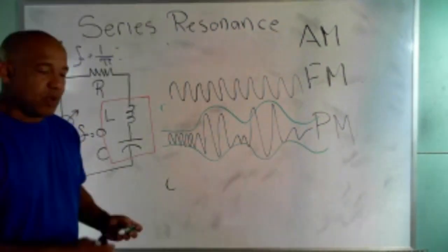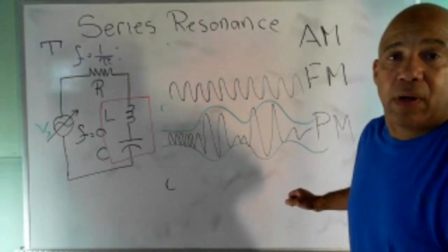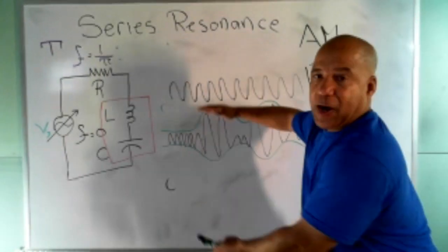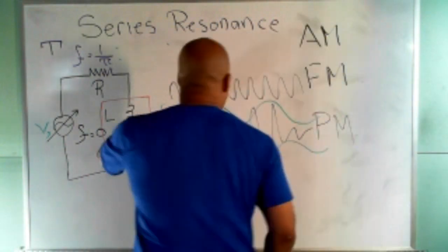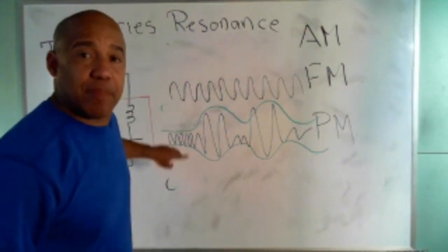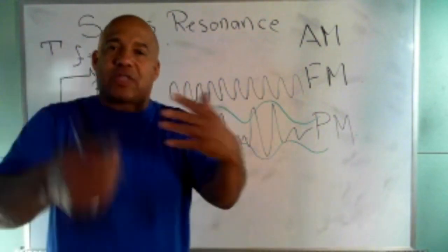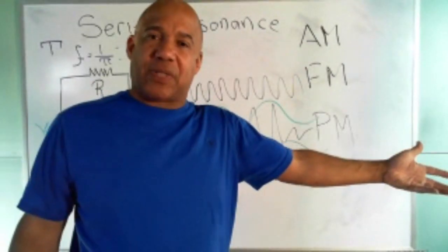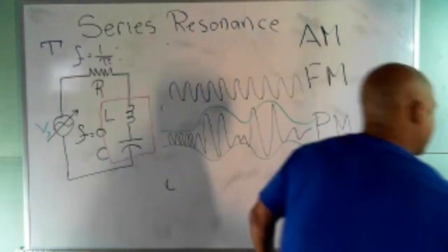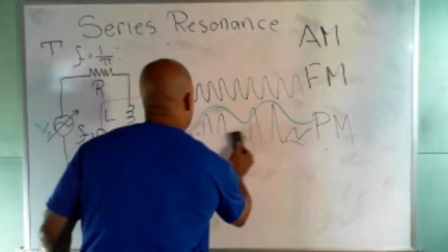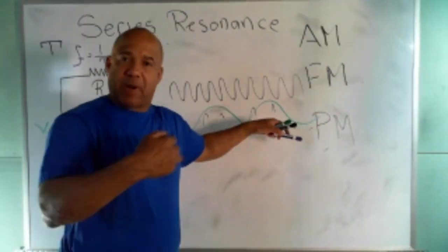And that, well, in radio electronics, communication electronics, this is called an envelope. So this varying is in direct proportion to my voice, but what you've done is at the top of the carrier and the bottom of the carrier, you created two other sound waves. And those sound waves are the audio that I just put on the frequency. I modulated the signal, so what I can do is take the carrier out, and I'm left with this. I take the carrier out, I'm left with that low frequency signal, which is the audio from my voice.